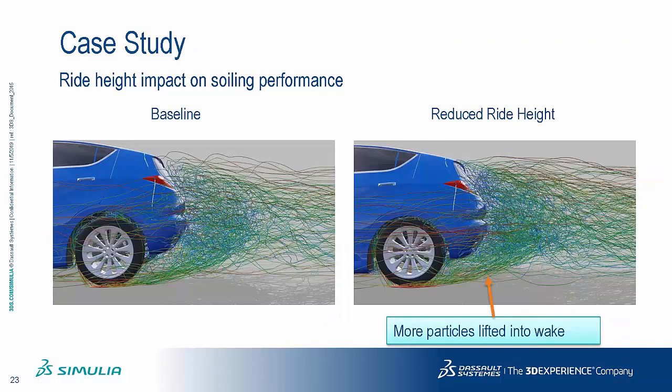Again, using those particle traces that I was talking about earlier, we can look at how the water is getting from the wheels to the rear face. And you can see here that a lot of that water is coming from those rear tires and it's kind of being pulled inwards towards the center. And that gives us ideas about how we could impact that. So for example, by putting rear mud flaps or by changing the bumper here, the rear bumper, we might be able to get better separation between the rear wheel wake and the base wake.